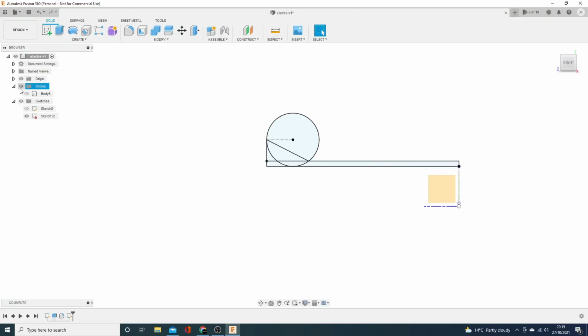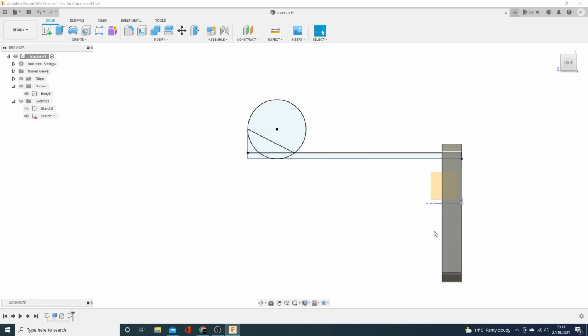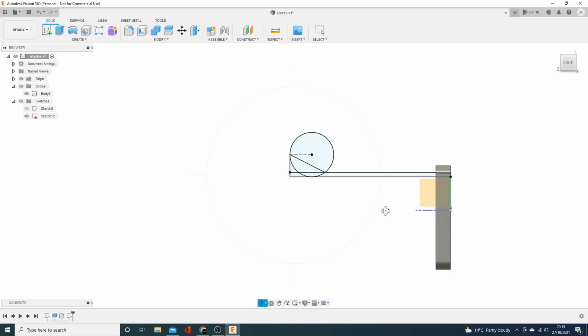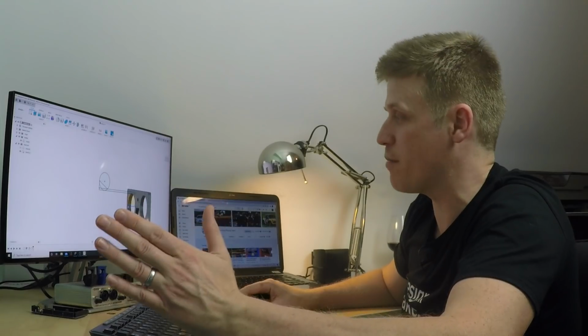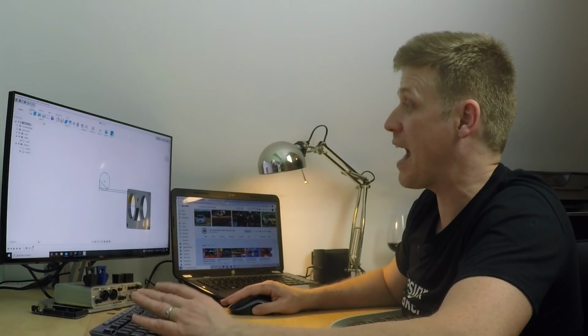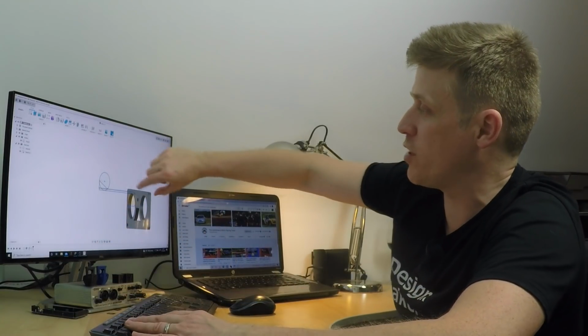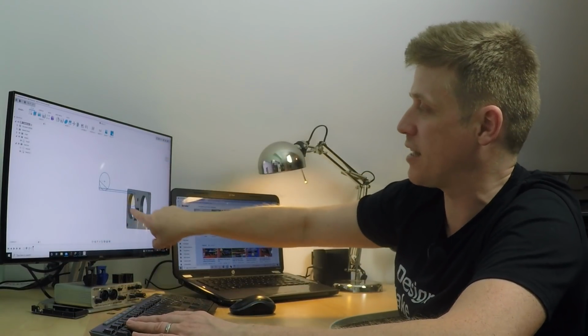So we bring the body back in. We're not going to extrude this. We're going to revolve it. So what that means is we're going to pick certain points, certain profiles, and then we've got an axis there, the Z axis, which is in the center, remember, of our inlet tract, and we are going to revolve this around that center line.